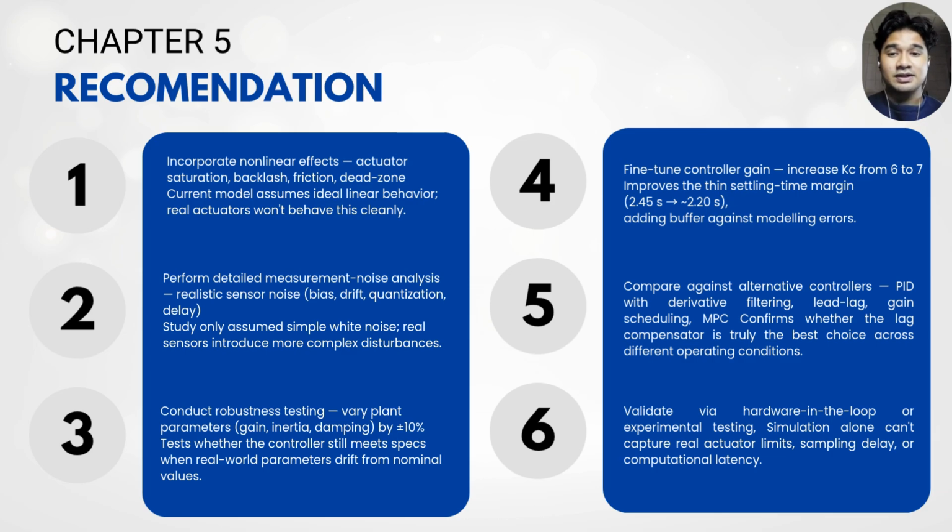For future work, several improvements are recommended. First, the model can be enhanced by including nonlinear effects such as actuator saturation, backlash, friction, and dead zone behavior. Second, a more realistic measurement noise model should be considered, including sensor bias, drift, and delay. Robustness testing under parameter variation should also be included to evaluate performance under uncertainty. In addition, increasing the controller gain from 6 to 7 may improve the settling time margin. Finally, hardware in the loop or experimental validation is recommended to verify the performance under real operating conditions.